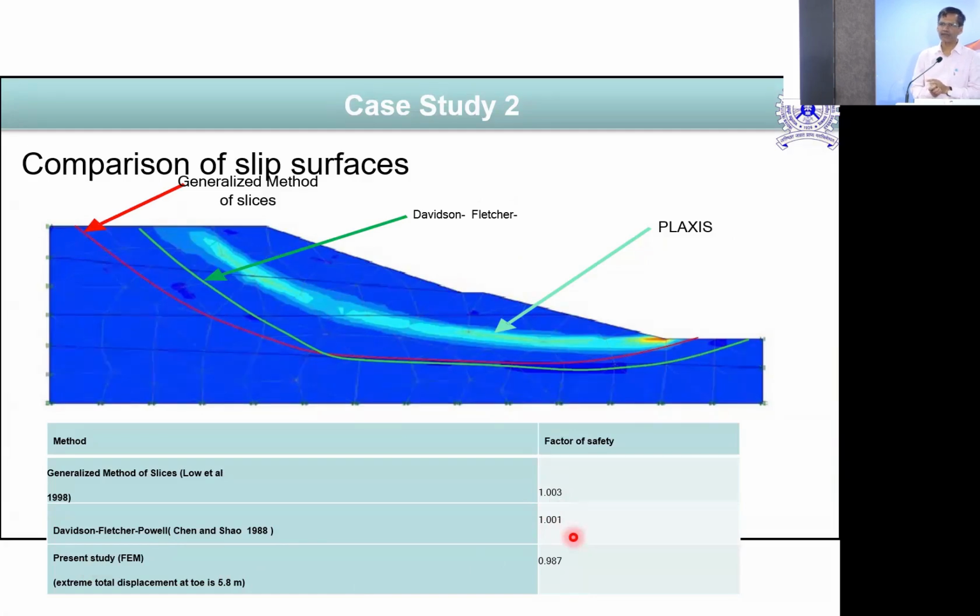It will not only give you factor of safety, but also stress, strain and settlement. Actually it should have been stress, strain and settlement. But obviously we are accustomed to factor of safety, so they have put this model in, so that if you use their software, you will get a factor of safety. Truly speaking, it would have given stress and strain because it is finite element based.